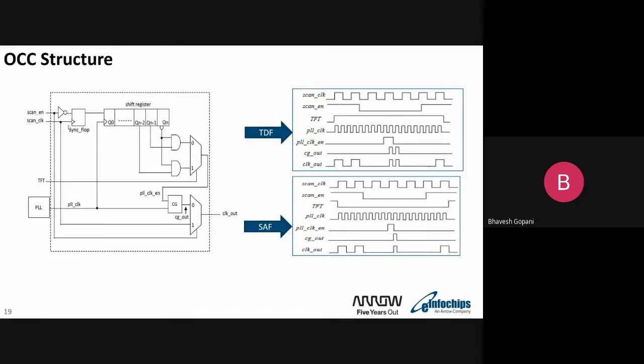The answer is, in my design, let's say I want to do at-speed testing. At-speed testing means I want to test certain logic with the actual functional frequency. So at that time I need to have the actual launch and capture cycles.